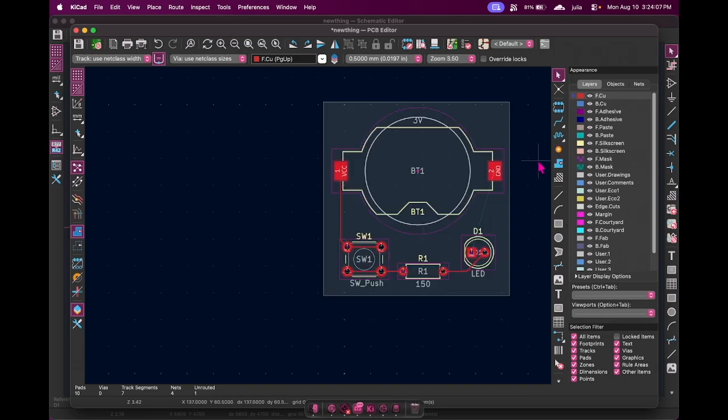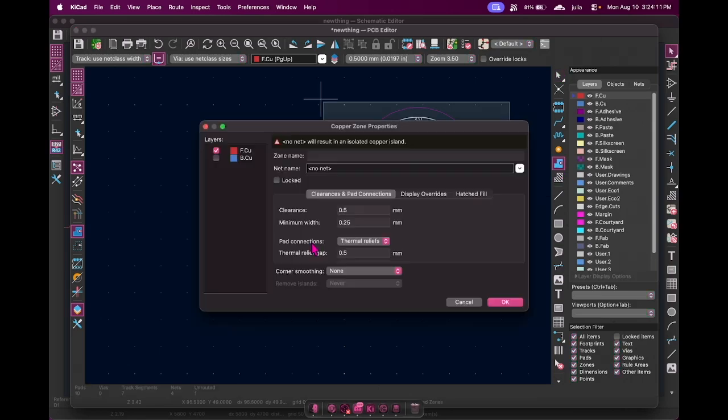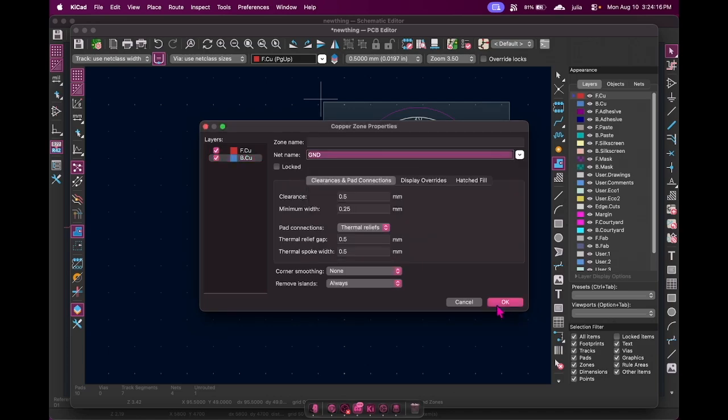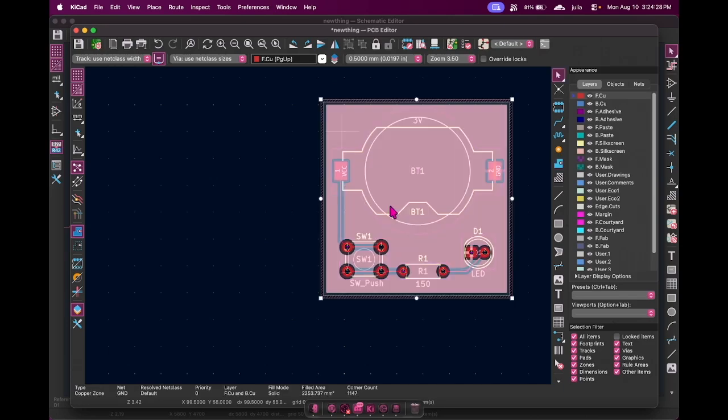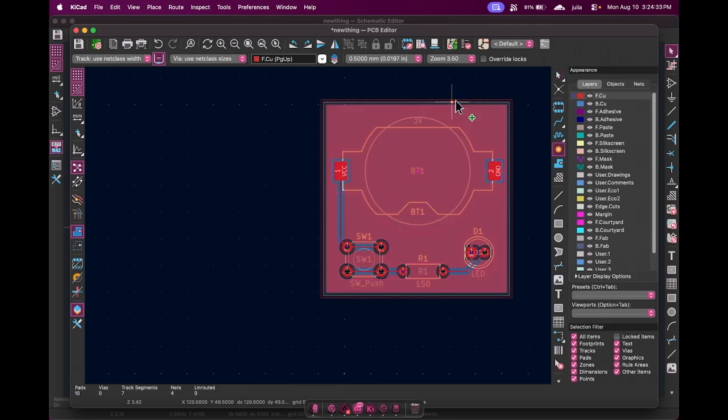Sorry, guys. Anyways, that's how you would use vias. But we don't need them here; I just wanted to show you guys the beauty of vias. We're still going to place some vias, but not in that way. Anyways, let's redraw our ground plane. Regenerate. Now we're going to place some regular vias. How do you regenerate? B. Oh, thank you. You're welcome.